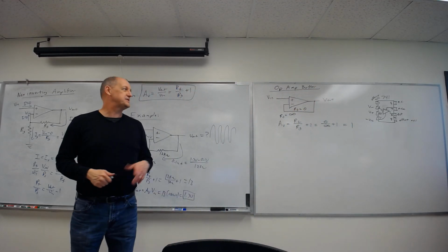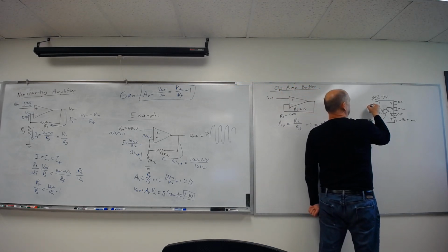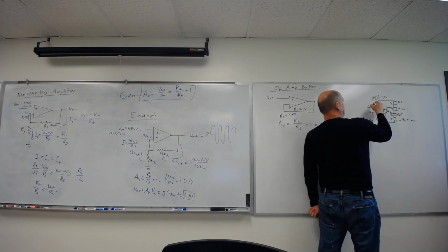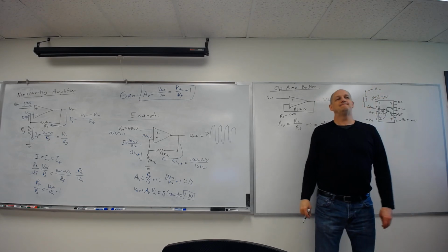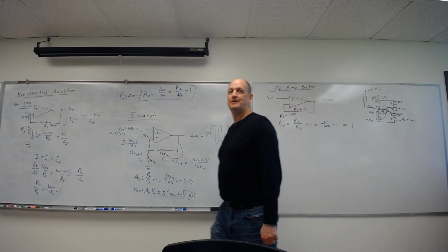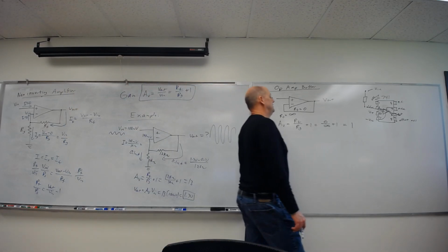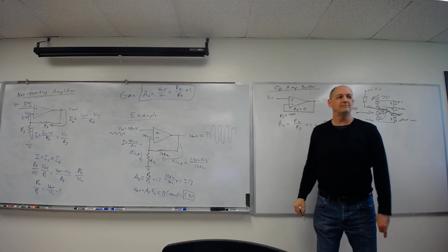So if I want to build my inverting amplifier, I'm going to come over, I'm just going to put a resistor right here and the feedback resistor go from output to input. I'm going to put another resistor over here and go off, not the power supply, but I'll plug my input into that. Two resistors. This won't work yet. You're going to connect that one to ground with a wire.